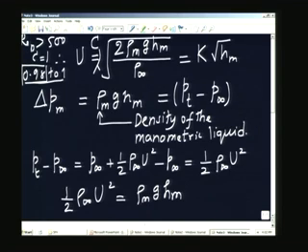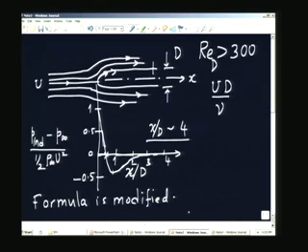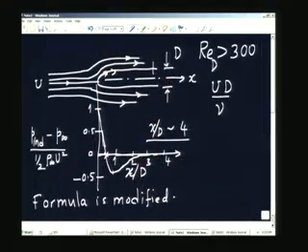And in fact, let me just discuss a little more about this friction portion. If you look at the flow around this body, if the boundary layer is very thin, the boundary layer theory tells us that the pressure across the boundary layer remains the same. That means that the pressure I am measuring is the same as the pressure in the main stream or the free stream here.